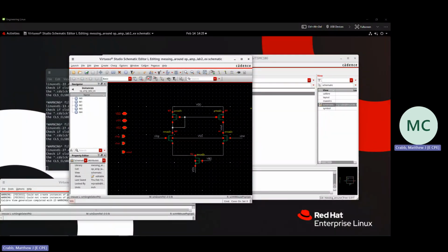Okay, it is. So in lab this week, we designed an op amp, and one of the most important specifications we wanted to hit were an open loop gain of, I think it was 40 dB or more, a gain bandwidth of 10 megahertz or more, and then an output signal swing of at least 0.5 volts peak to peak.